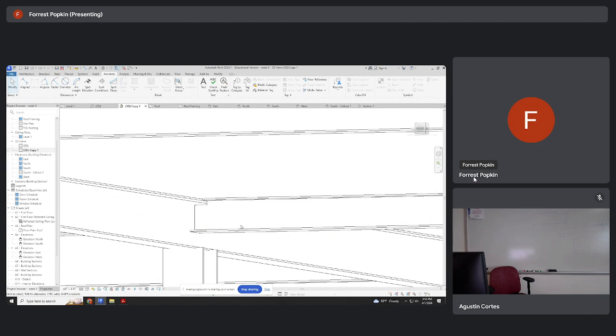Does that make sense? So basically, in summary of this particular nugget, we should understand how to cope things as we put them together, be able to manipulate levels, okay? Be able to pick the plane we want an object on, know how to go to our reference library and download additional beam sizes, understand that we have annotations for structure that should be in a different folder, used for just drafting lines and details.